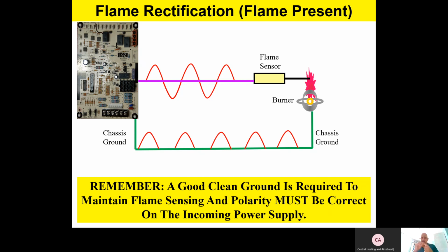And the very next time you put it in the flame for sensing, that sand can actually melt into a glass type of component. That's what glass is: melted sand. So we recommend that you always use Scotch-Brite or stainless steel wool for your flame sensor. To clean the flame sensor, do not use sandpaper.